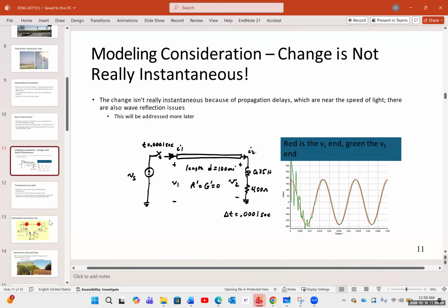Now, another thing that we have to consider is the limit that you have on a transmission line. Imagine you have a 10 millimeter thick wire in Houston, and the same wire in Amarillo, they have different limitations. In Houston, we have higher humidity, higher temperature. When you have higher temperature, your limit is actually lower compared to the same line in Chicago or Toronto or something like that in Canada. So temperatures also vary in summer or winter. The amount of load that you can put on a system in summer is different than what you can put in winter.